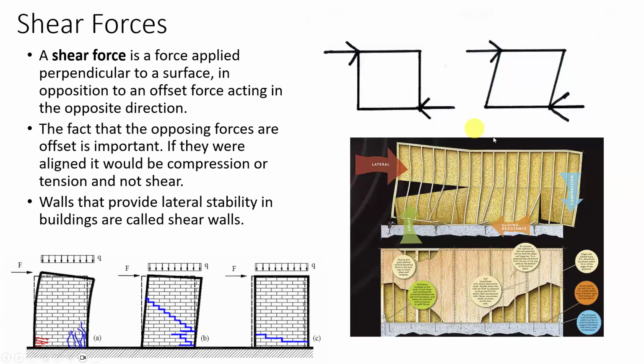So on a commercial building like this where we don't use wood, you probably notice when you go into our stairwells, those walls are all concrete block. Those are shear walls. So those walls being block, they provide that shear strength that keeps this building from wanting to tip over if there was a strong enough wind against it. So the floors transfer the load to those shear walls, and those shear walls try to stabilize the building laterally.